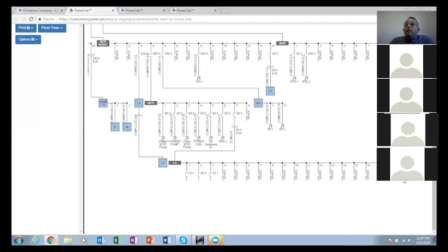Now, you asked earlier about the auto function and what it also does for you. One of the reasons we have the auto and the manual is that some engineers have their own preferences when they design. So even though the NEC is giving you the minimum value, some engineers go ahead and play it safe, say, you know what, instead of a number 12 conductor, I want it to be a number 10.